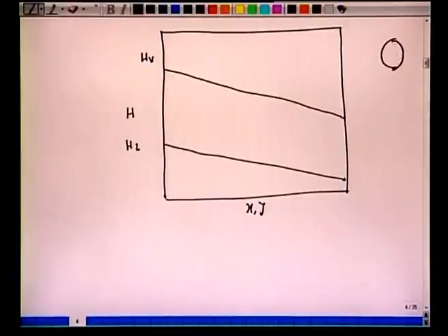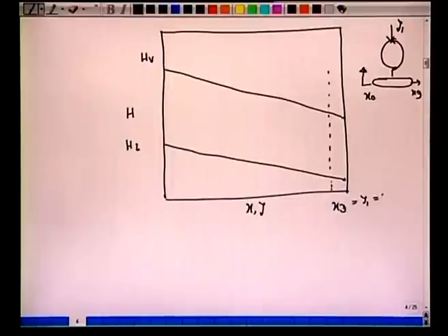So we have the condenser here, total condenser, and the vapor composition was Y1. It gets totally condensed, we have separated, and we have 2 streams product. This goes as a reflux. We have X0 and we have this XD. So this quantity we calculated, these mole fractions: XD equals Y1 equals X0 equal to 0.74.